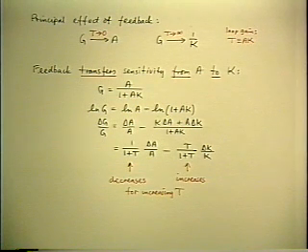Something very fortunate happened in that, because the main reason that Black introduced negative feedback, or began to think about the idea, was to overcome the lousy properties of the vacuum tube. Two of them: nonlinearity and gain variation. And feedback helped a lot.